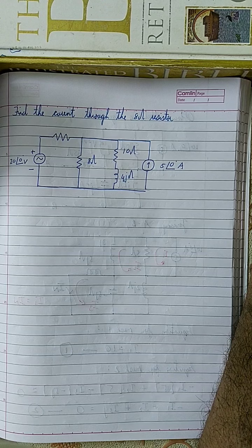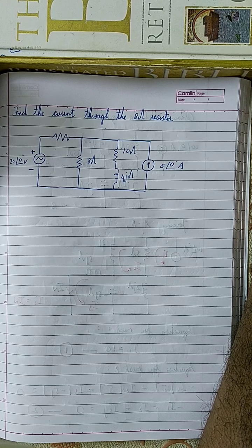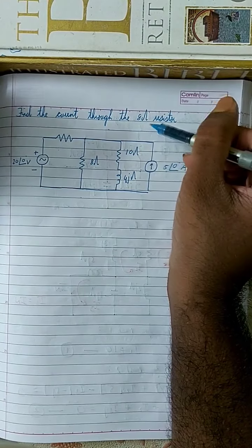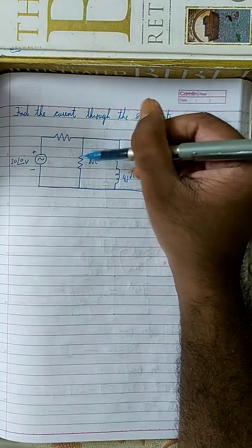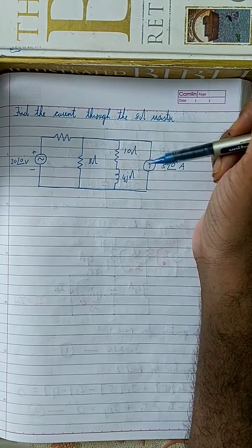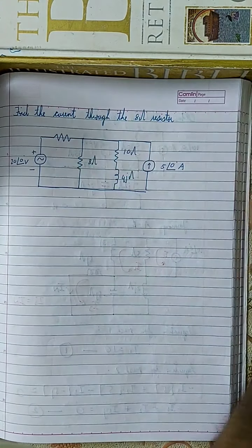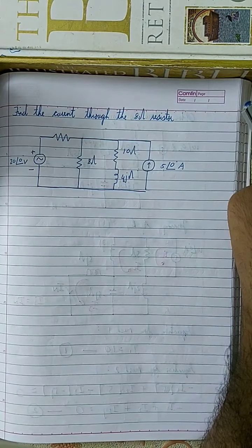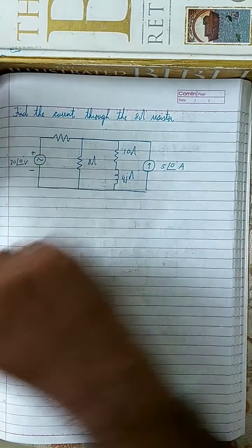Here, first, as usual, the same way we do for Thevenin's theorem, we look for the load. The question is with regard to the 8 ohm resistor, which means you need to treat this resistor as your load, which means you need to remove this resistor. And since you are applying Norton's theorem, after removing this resistor, you short the two terminals.